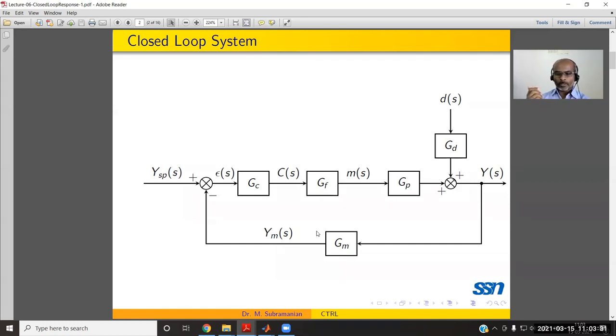Using this simplest form of controller, like the PID controller, we discussed the role of proportional action. With the proportional action, we had seen that we could not eliminate offset. There is a persistent offset. To eliminate that, we tried the other mode of controller, what is called integral action. With integral action, the overall order of the system increases. For example, a first order system turns into a second order system. But we know this second order system also introduces what is called cyclic behavior.